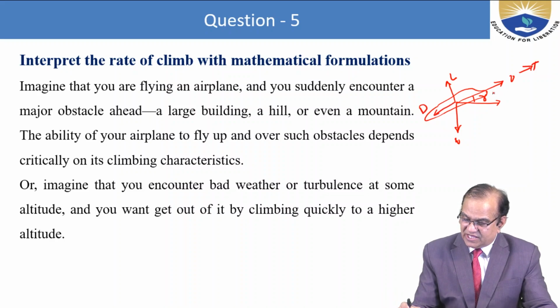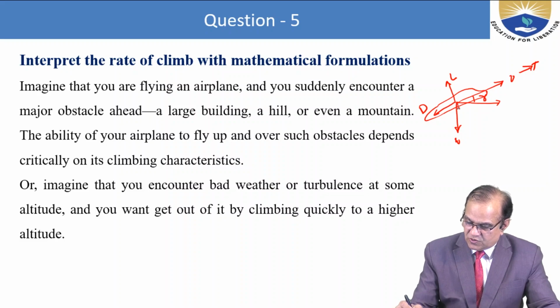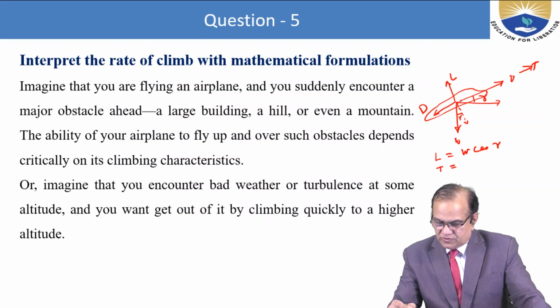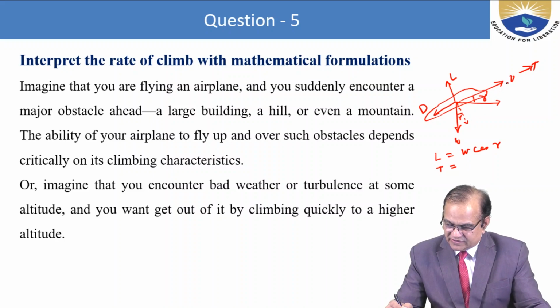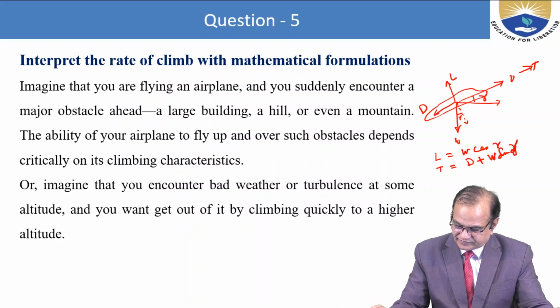If I make the equations for this, lift is equal to W cos gamma, and thrust is equal to D plus W sin gamma.